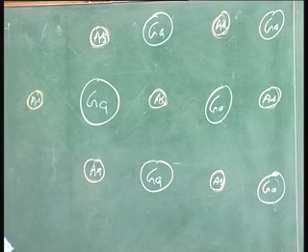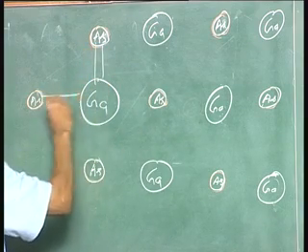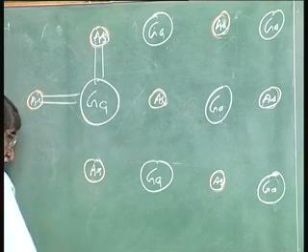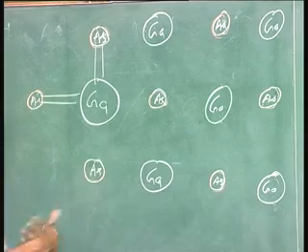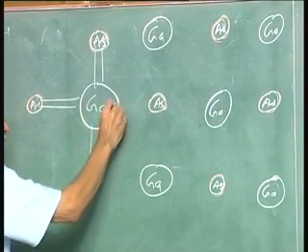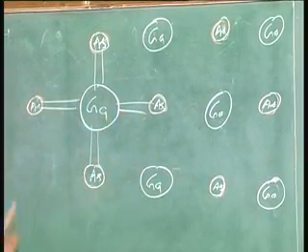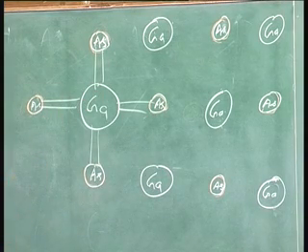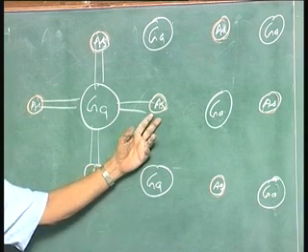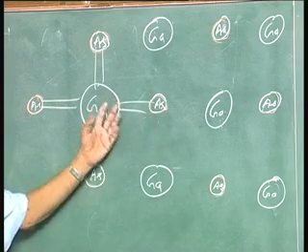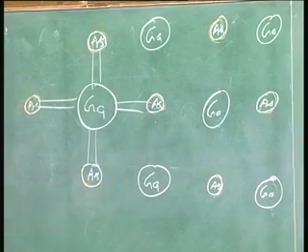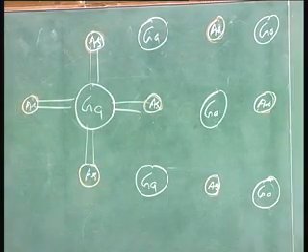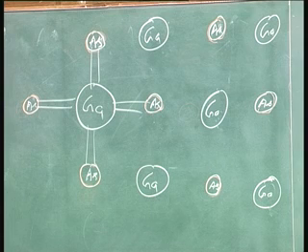Now, you can see that the bonds are like that; you put 2 to show that on average it is 2. In silicon, you put 2 like that, total 8 electrons. Right? These are the electrons which you represent, which form the bond. Now, arsenic has 5, therefore one of the electrons will be slightly displaced partially towards it. So, there will be slight electronegativity, a negative charge on arsenic and a positive charge on gallium.